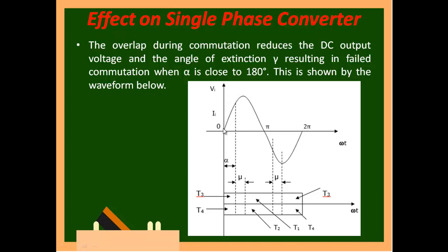See here, your negative thyristors will try to switch off, but since there is source inductance, they continue their conduction until the instant where I have turned on T1 and T2. So there is simultaneous existence of all four for a particular duration of time. Then T3 and T4 will vanish. So this is the region where both positive half cycle and negative half cycle switches are in conduction.